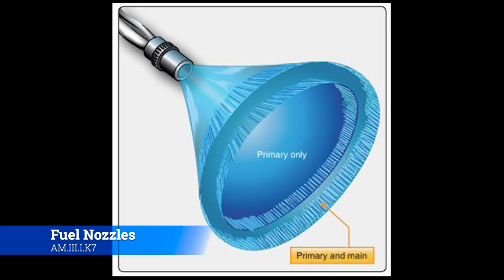Now, there's a lot of physics into why that works the most optimum way, but the so what for our scope of knowledge is that it needs to follow that exact pattern. And the maintenance manual, whenever you go to work on one of these, will tell you that. It'll simply say, hey, look, it needs to look just a certain way, look for these particular things. Now, if there's any deviation from that spray pattern, what you're going to end up having to do is clean it. You'll take the spray nozzle out, you'll clean it if the maintenance manual hasn't already told you to.